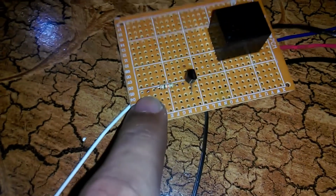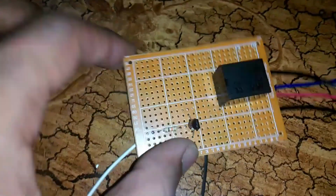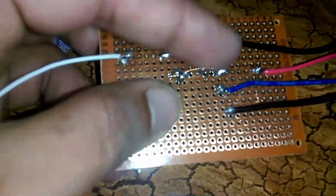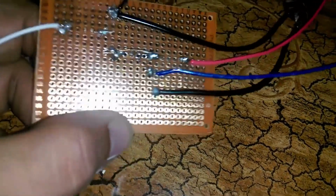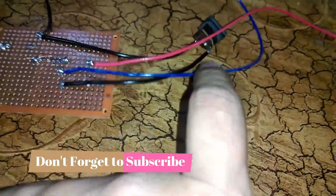This is a 10K resistor which is connected with the base of the 2N2222 transistor, and this is the emitter, and this one is the collector. As you can see, the collector is connected with one side of the relay coil, and the other side is connected with the positive.